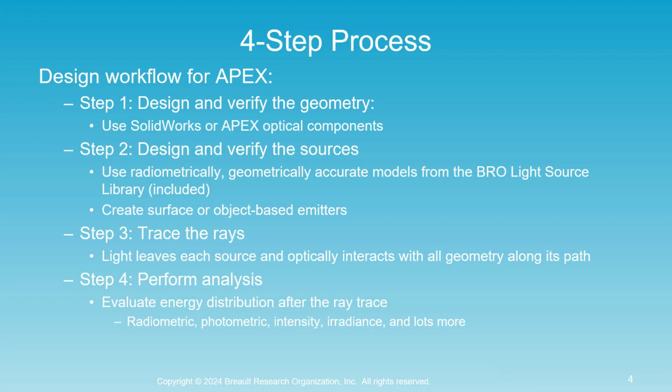Breault has come up with a simple 4-step process for Apex that can be applied to any task and will be used in future examples. These 4 steps are designing and verifying geometry, so mostly SolidWorks and CAD, but there's a little bit of Apex in there as well. Designing and verifying sources is the next step, which is where Apex mostly comes in. Then tracing the rays, and finally performing analysis on the system. These 4 steps will be shown in detail when examples come up later.